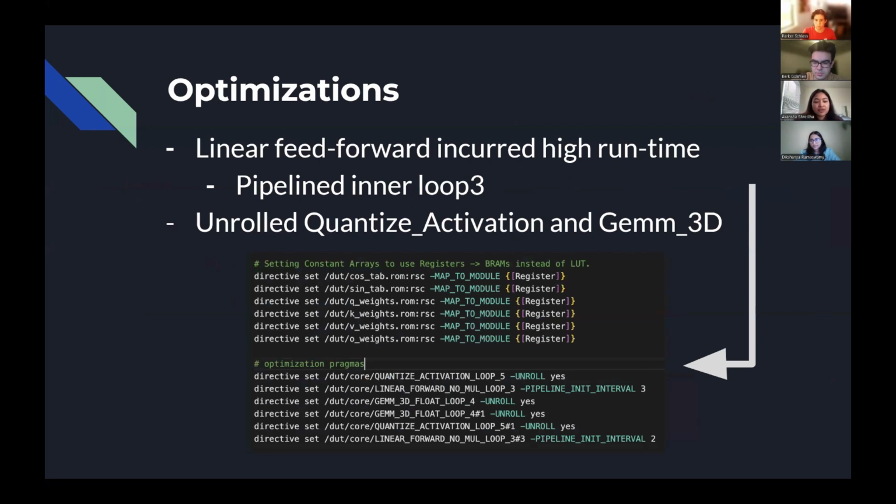We tested the design for an FPGA specifically for the attention layer using the data that was a quarter of the original size. Initially, the direct implementation of the algorithm made compatible with Catapult overutilized FPGA resources, with LUT usage reaching approximately 106%. Upon analyzing the report, we identified that constant arrays such as weights were unnecessarily being mapped to LUTs. Leveraging Catapult's features, we remapped these constant arrays to utilize BRAMs instead. This optimization significantly reduced the area utilization, decreasing it by 4 times.